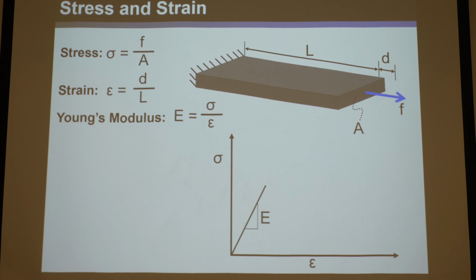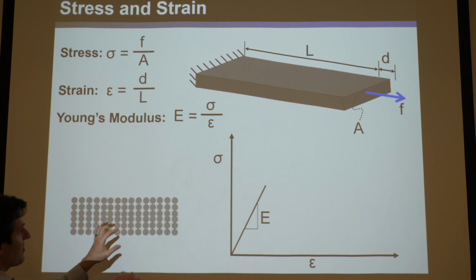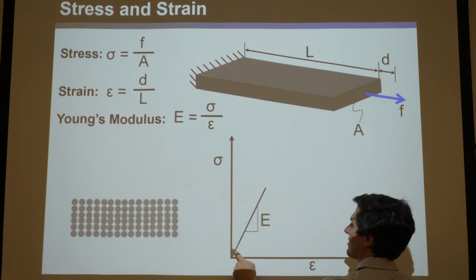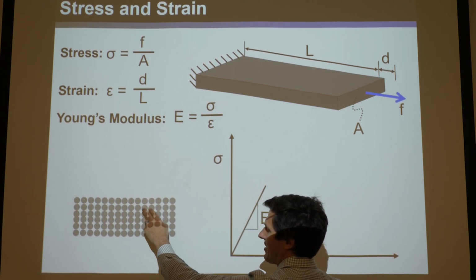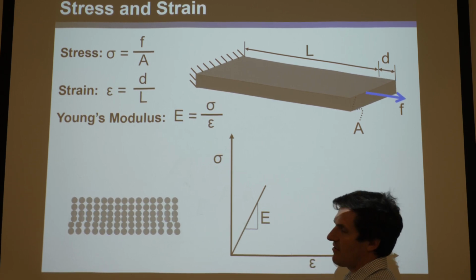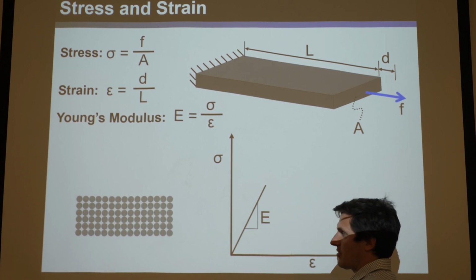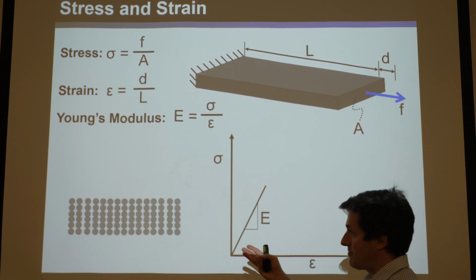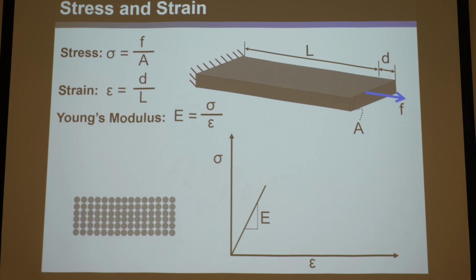All right, so what happens here, if you were to animate this picture zoomed in on the atoms as it elastically goes up and then bounces back down along this straight line, is that each independent little atom gets stretched, and their atomic bonds behave like springs. As long as you don't break any of those bonds, as long as there are no propagations or dislocations of those atoms, then they bounce back to right where they came from, and it just goes back here, which is, by the way, why compliant mechanisms are very precise, right?